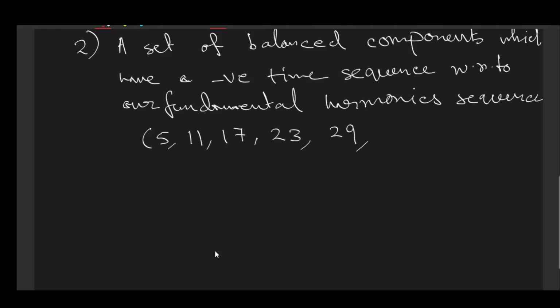Why are we considering odd order? Because we have already discussed that our windings or transformers are so constructed, or the topology of the circuit is such, that they always produce waveforms having half wave symmetry, irrespective of whether it is an even function or odd function.